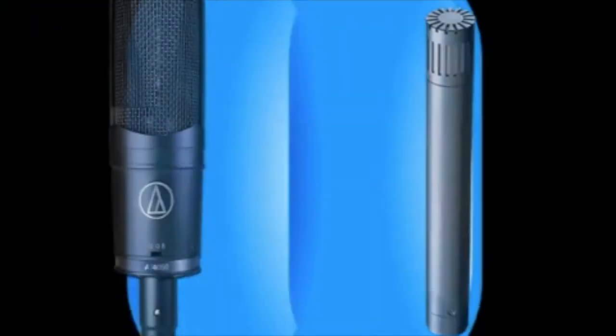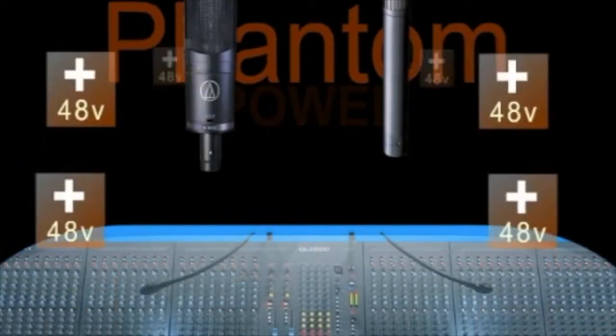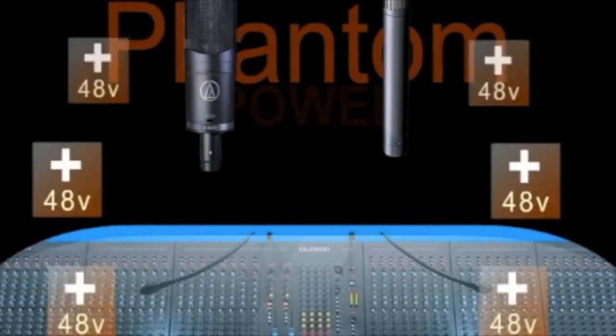Condenser microphones require an electrical source to function, called phantom power. Phantom power is a 48-volt DC voltage supplied by a preamplifier. Preamplifiers on most mixing consoles commonly have phantom power.